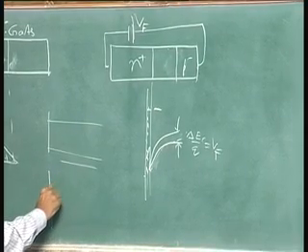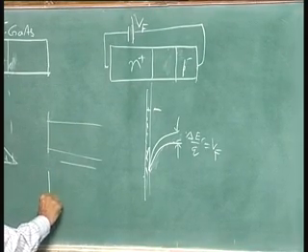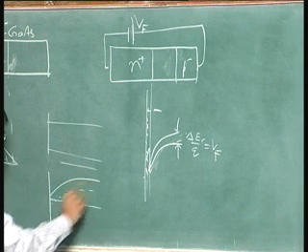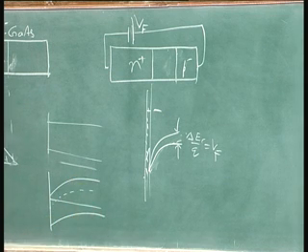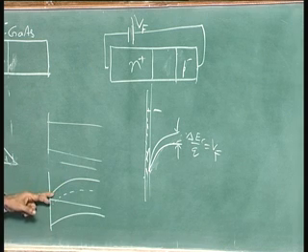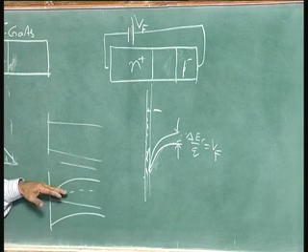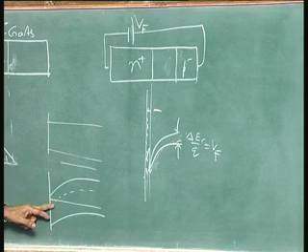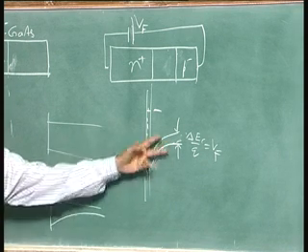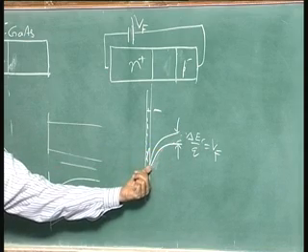You have to visualize that how much it is n type depends upon how much it is bent. If it bends less, it becomes less n type. In this case, it is a similar argument. If it bends less by forward bias, the number of electrons in the notch is less.